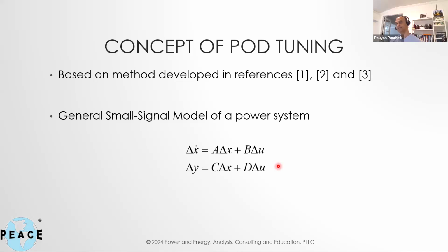Everything's differential equations. They're frequency domain models for transmission lines. If we come to a phasor domain model, all that stuff goes into the algebraic equations because we assume they're lumped constant impedance values. So the inherent nature of the equations is still the same. We've got differential equations and we've got algebraic equations.